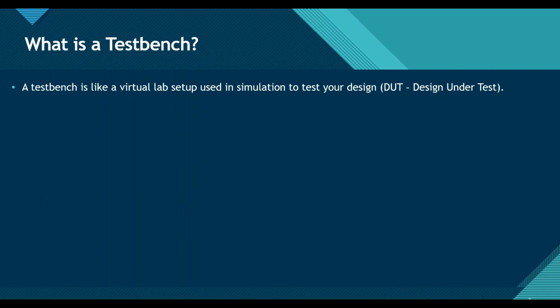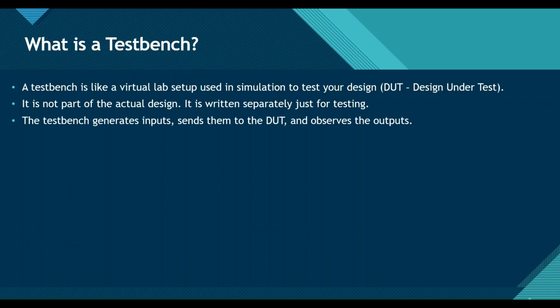What is a testbench? A testbench is like a virtual lab setup used in simulation to test your design. It is not a part of the actual design. It is written separately just for testing. The testbench is used to generate the inputs, send them to the DUT, and observe the output.